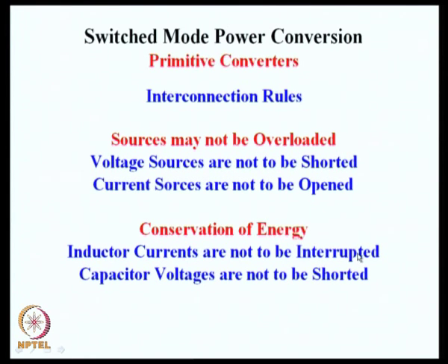And the dual of this is that the voltage across the capacitor is an energy variable. The capacitor has a stored energy of half CV square, and if the capacitor voltage is interrupted or short circuited instantaneously, the capacitor energy is also killed instantaneously, and these are not to be done.